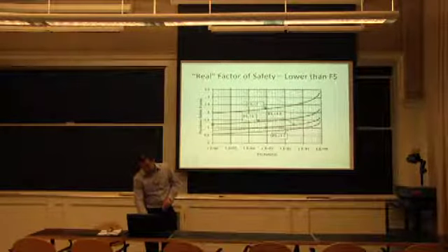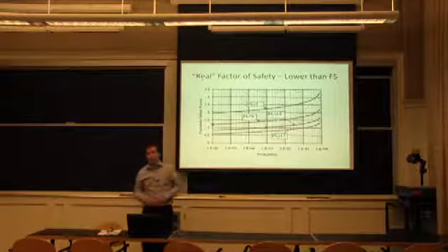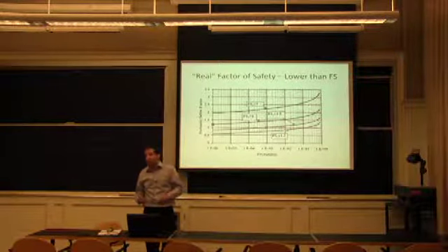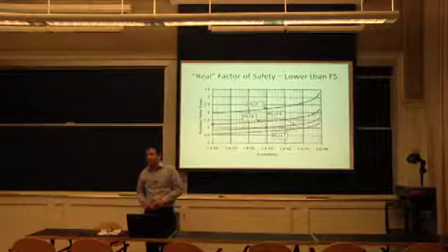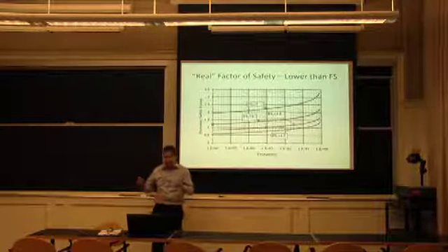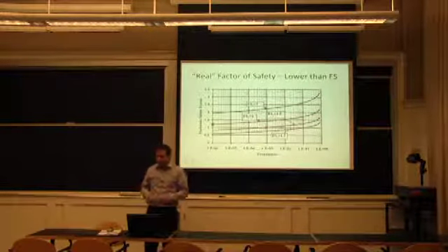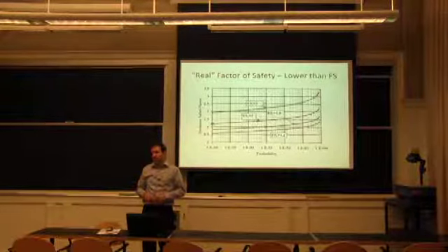Or the roof joist, you start with 2, and then the guys screw up the welding, and then you're close to 1, right from the get-go. You just don't know how likely it is that all of this will happen. But over time, your safety factor is going down. And it's not because you start with a safety factor of 3 that 2-3 years down the road you can say, oh yeah, you can put 20% more load on it.